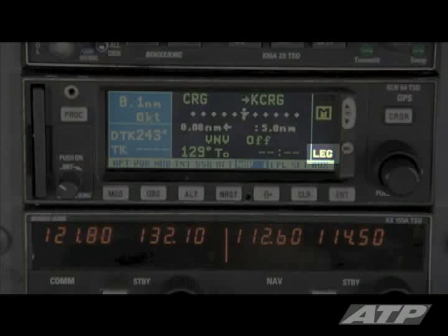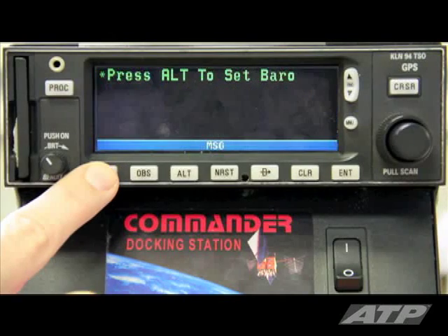The right column of all nav pages will enunciate the different modes and statuses of the GPS. You will typically see the GPS in leg mode, but will occasionally need to change it to OBS mode using the OBS button. This column will also indicate whether in terminal mode with the approach arm message or approach mode with the approach active message. Whenever a yellow M appears, press the MSG button to read the message and comply with any instructions.